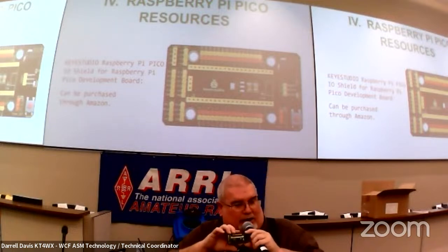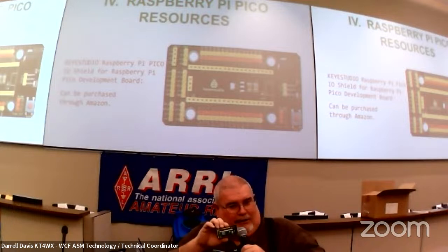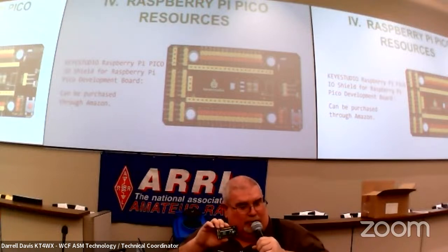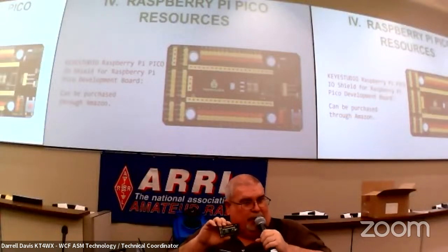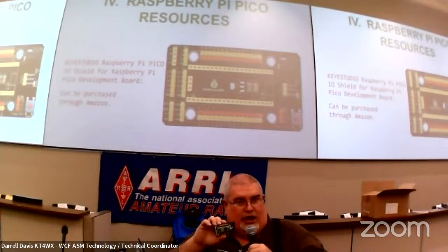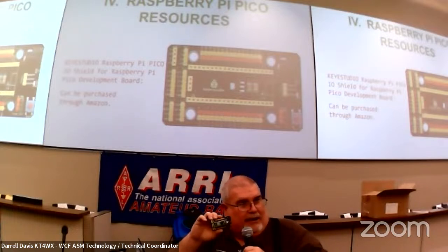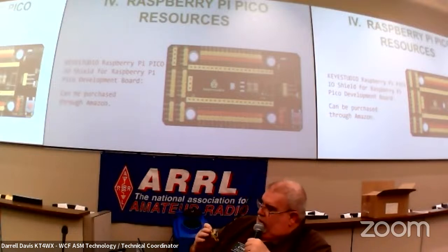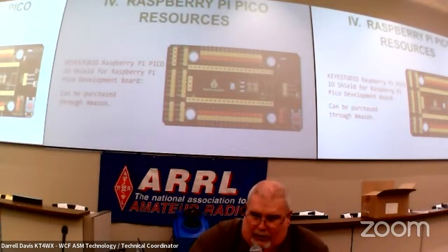Now, it's a good thing you're not designing anything high frequency, like Gordon talked about today with the SBITX. They didn't drop in enough caps in places, and it actually produced spurious oscillations that were not supposed to be there. The original SBITX had a problem. It destroyed the finals through VHF parasitics. And they've gotten through that and have resolved that since then. But it's good. And this board, by the way, you're going to like this.